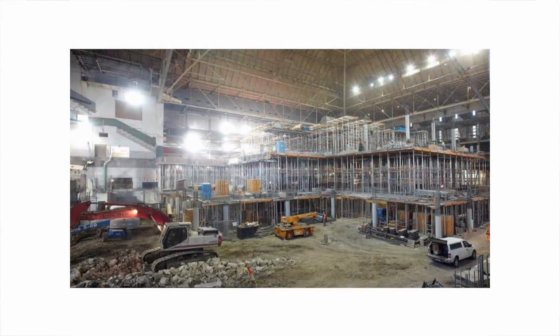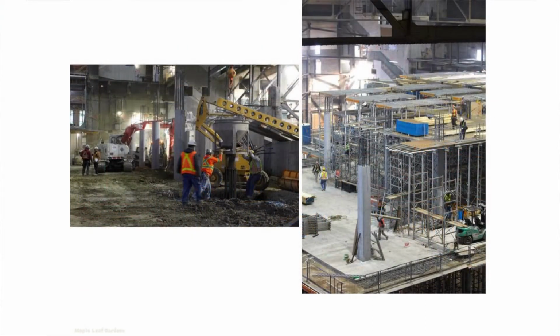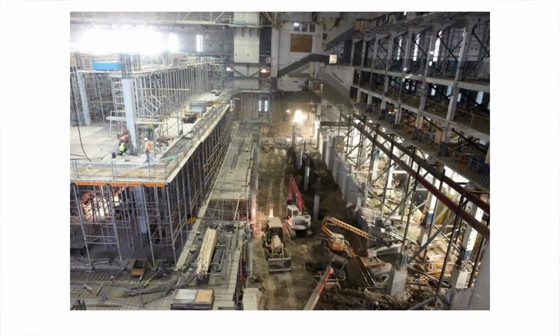So here you can see an actual construction photo from, I'm going to say about 1.5 years ago. You can see on the side all the stands were taken away. You can keep going, V. So you see quite a bit of the reshoring, underpinning, temporary work that needed to be done to keep the exterior walls up while all of this interior work was going on. So it's actually quite complex. All the structure there on the right-hand side is all temporary, that once the floors were put in place, we're going to be taken out.